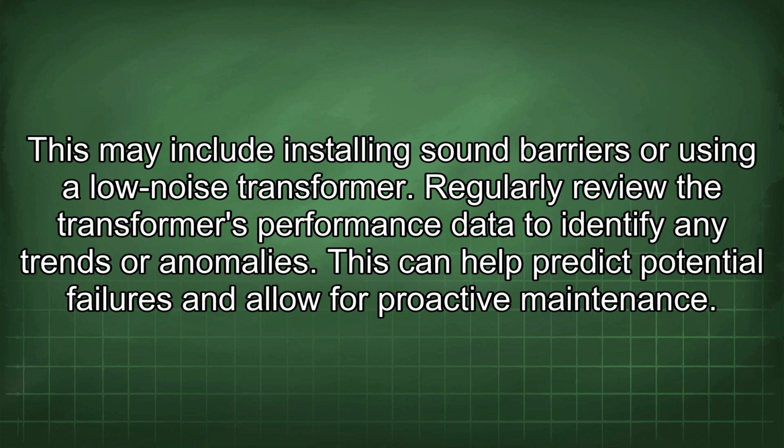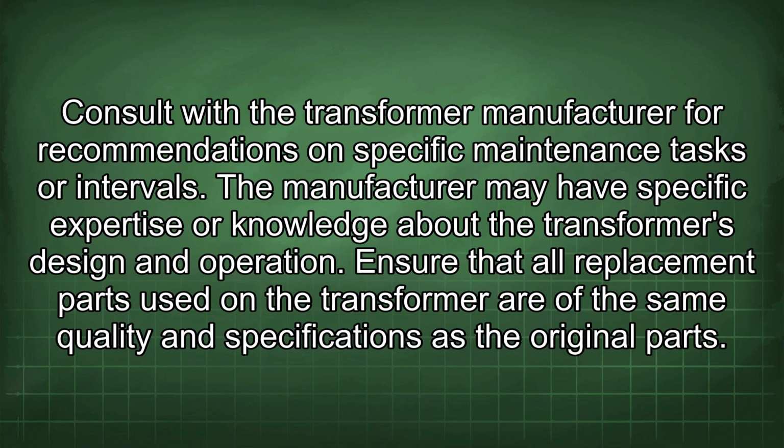Regularly review the transformer's performance data to identify any trends or anomalies. This can help predict potential failures and allow for proactive maintenance. Consult with the transformer manufacturer for recommendations on specific maintenance tasks or intervals. The manufacturer may have specific expertise or knowledge about the transformer's design and operation.